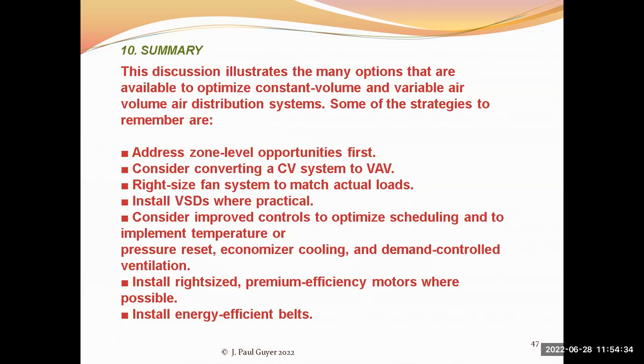And again, have there been other energy improvement features incorporated into the building, like more efficient lighting, solar glazing? And if so, that's probably reduced the total load on the air conditioning system, and you may be able to reduce the fan size and thereby reduce the energy consumed.